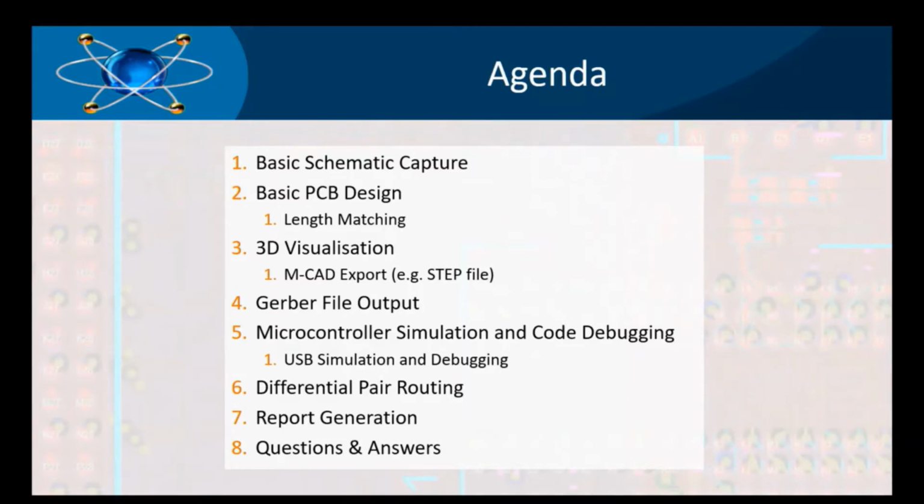So the agenda for our presentation is that we're going to do a walkthrough in Proteus of some basic schematic capture, some basic PCB design including length matching, some 3D visualization including exports of the 3D in STEP formats or otherwise, go over file output of course, and then some microcontroller simulation and code debugging including USB simulation and debugging, some differential-pair routing, some high-speed design features there, and then some report generation.